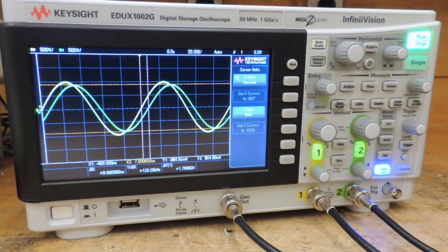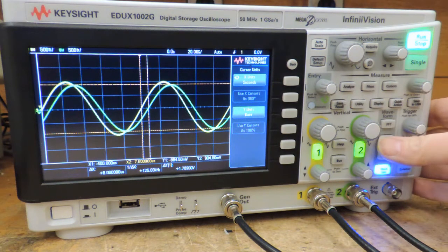So continuing on under procedure step number 3, we now want to measure the voltage drop across the resistor. What it says is, using the math function, measure and record the voltage and time delay for the resistor. That's Vin minus Vc. And then we're going to compute the phase angles, record these values in table 6.2. Just to remind you on how to do that, we did do that in lab 3, how to use the oscilloscope. So what we do is we go to the math function,